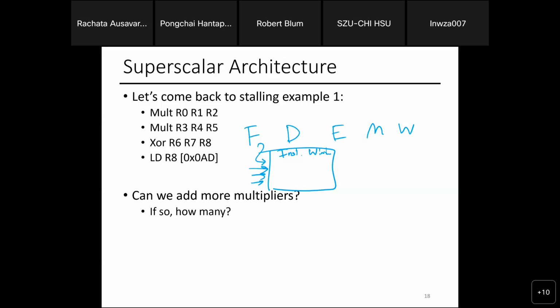Oh, then in that case, pipeline stall. Yeah. Let's say there's a common thing. For example, your code will be like add, right? Then maybe 3 multiplies consecutively, right? In that case, you're going to see add, multiply. If you have 3 adders, 3 multipliers, everything can be fed to those units right away from the window.